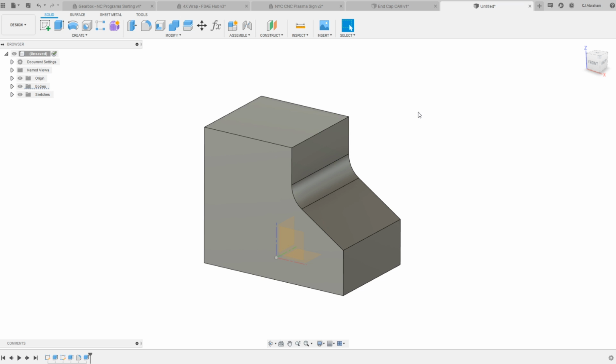Okay, so this is something that I've come across before when I was making real parts for my job. But I want to finish this surface, but I need to use a 2D contour so I can use wear compensation so that this face is within tolerance, right? I might have plus or minus on the tool wear. And this is something that you can't necessarily do with a 3D parallel toolpath because the 3D finishing toolpaths don't have cutter comp. So here's what I'm going to do.